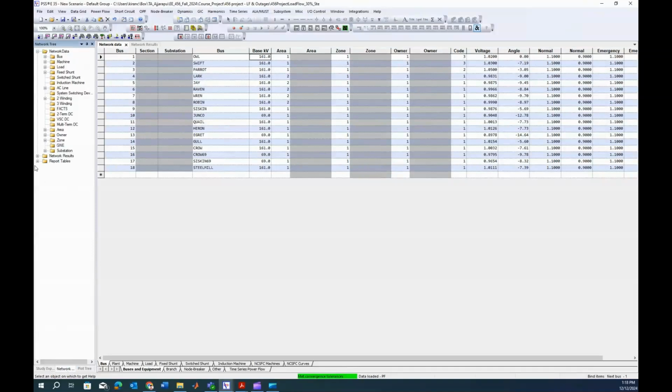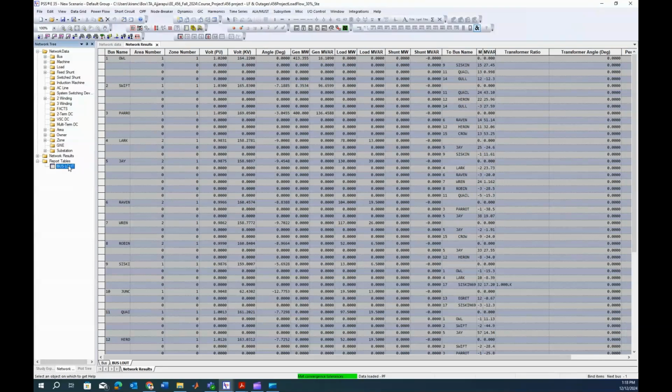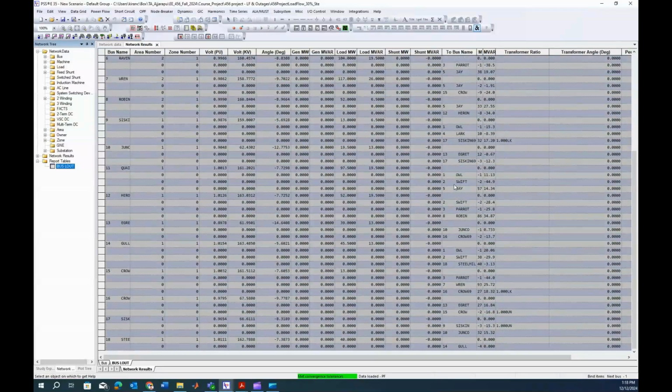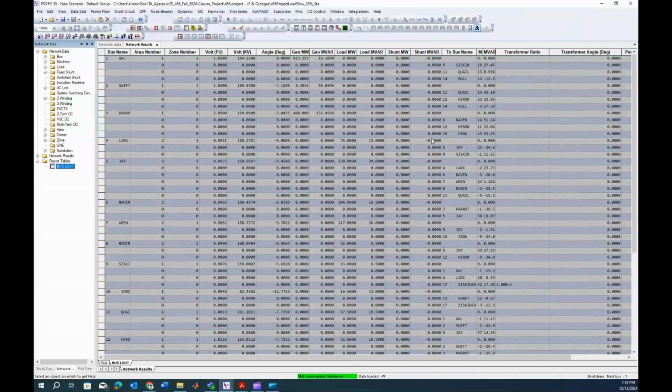And when you go at the bottom, this is the study report, but in the network, you can have a look, there is an option called reports. And on that, if you click on bus plot, that will basically update here. This is basically the results that you have, which you can utilize and analyze and understand what the power flow solution is for this particular case.